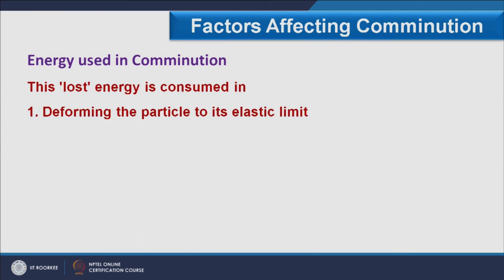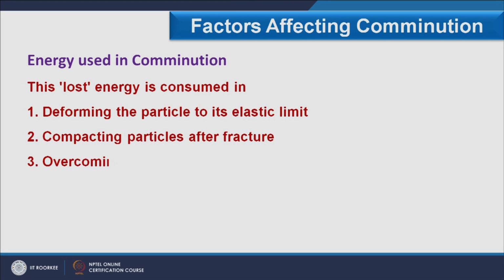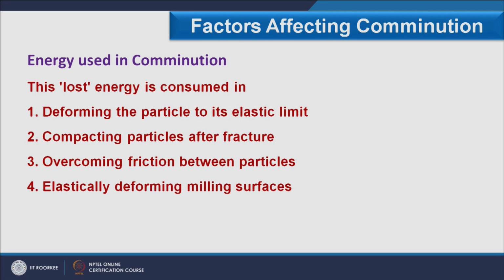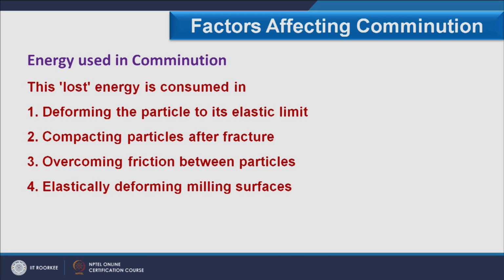So, where does the rest of the energy go? Energy is lost in deforming the particle to its elastic limit, compacting particles after fracture, overcoming friction between particles, and finally elastically deforming milling surfaces. So, in these 4 ways the energy is lost. This energy is dissipated as heat.